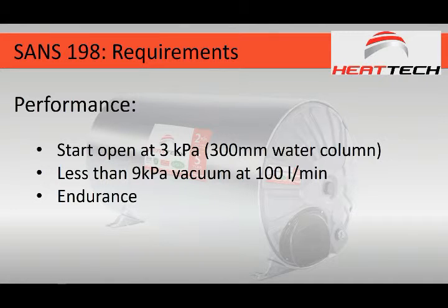Now at this stage, I want to repeat the fact that a vacuum breaker is one component in an overall system. If you fail to install the correct vacuum breaker, or if you fail to install it correctly, it can cause the product not to work, which means where there previously were 2 or 3 maybe safety checks before something can really go wrong, if you haven't installed it correctly, you take away one of the safety checks and you make it 50 or 30% more likely that if something else goes wrong, it will have a negative effect on the overall installation and could cause contamination.